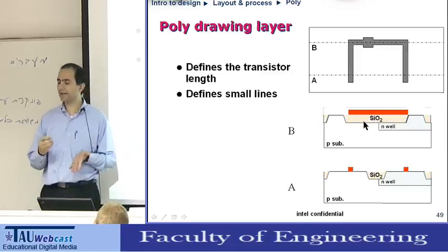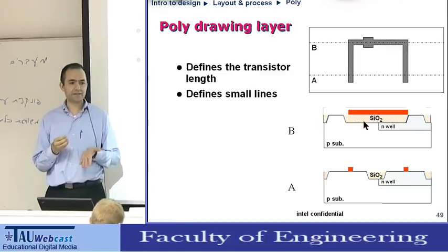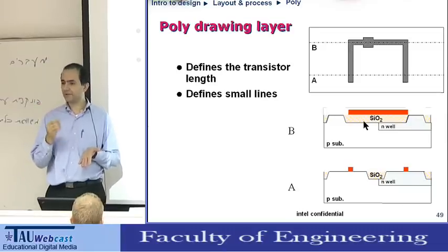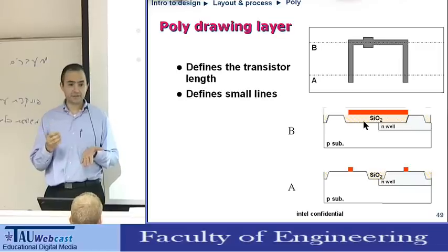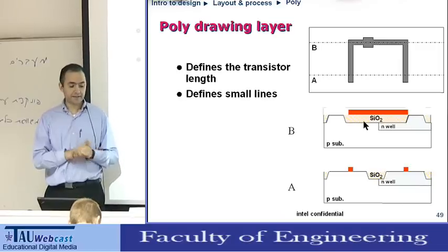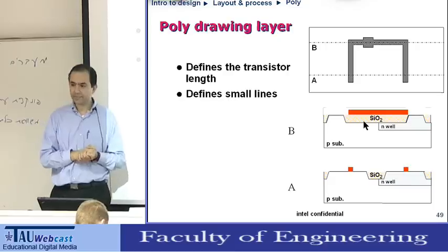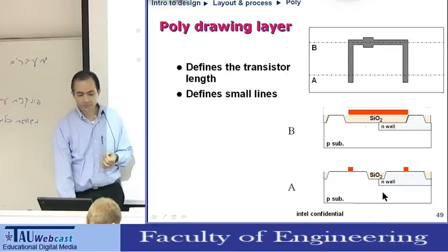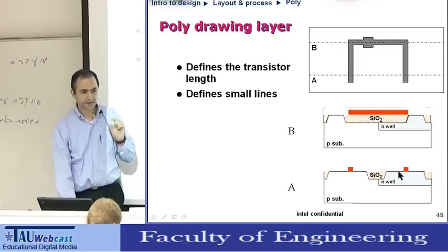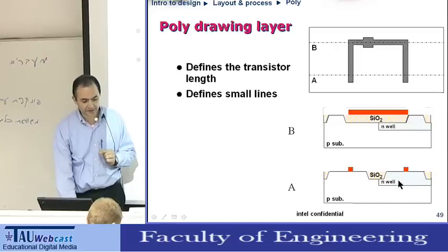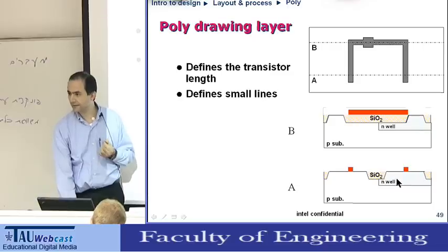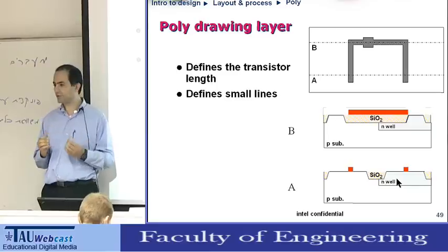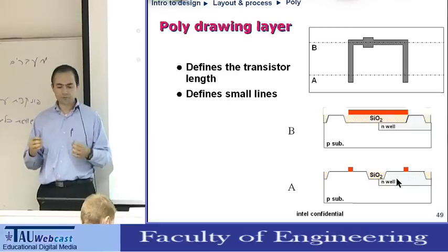So we will use an etch which is selective, so it etches silicon and it does not etch oxide. Okay? And then what happens if that etch will suddenly etch oxide? We will punch through the thin gate oxide and we will start etching the silicon of the wafer itself. So it's very critical in this step to have an oxide which is selective. So we will etch with the selective etch.